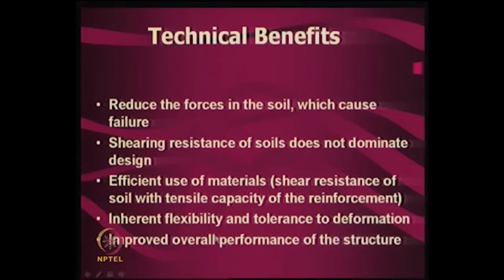Then the other important point was the inherent flexibility and tolerance to deformation. Because of this advantage, it is much more flexible and the earth pressures adjust themselves, and the deformation tolerance is very high. In some cases, some retaining walls cannot take deformation, they may collapse, but here there could be deformation, but then it could stand.